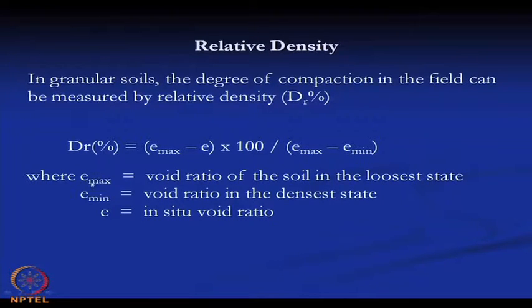So, if we know the e max, e min and e at any condition, then we can determine the degree of relative density of the soil at that situation.